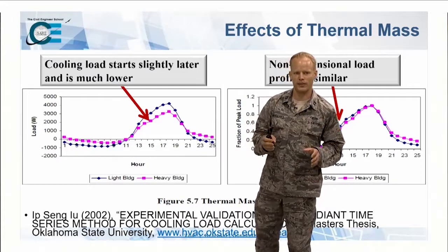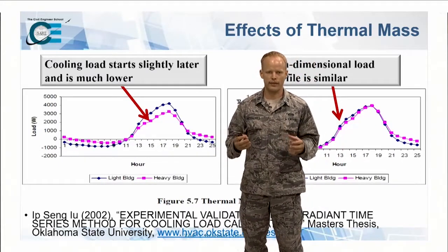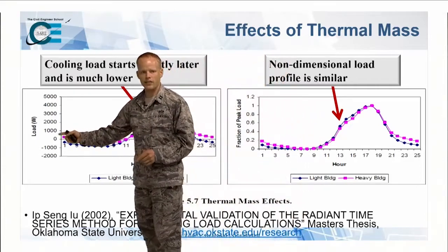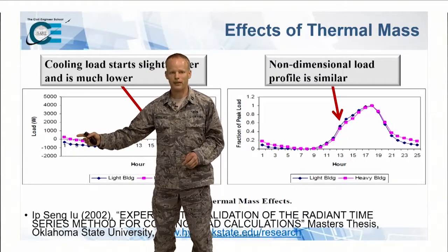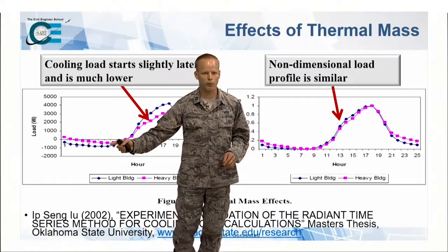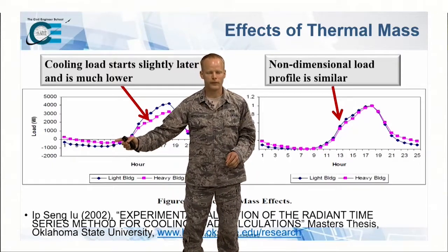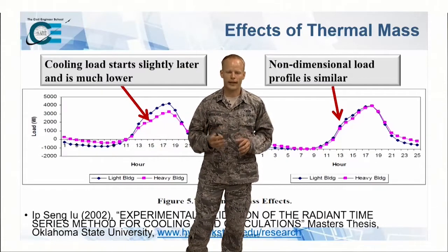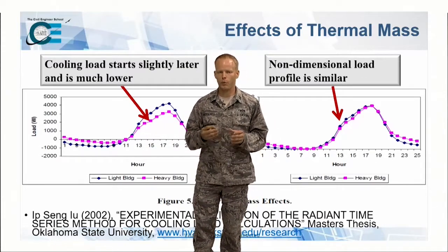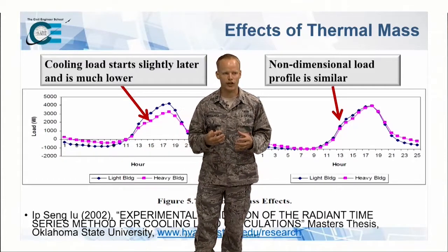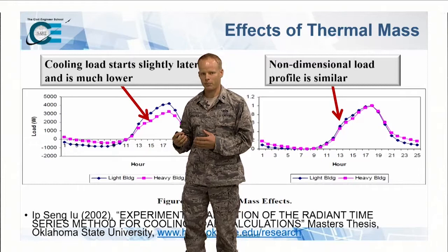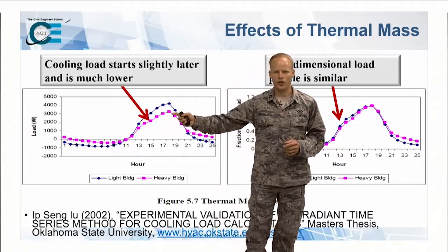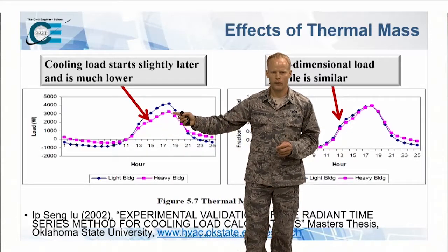But if we have thermal mass, well, at night, that thermal mass is going to get colder, and it's going to continue to get colder. So we look over here, and it doesn't decrease as much, following the purple line or the pink line. It decreases slower, but when it's here, now they're even. So when the temperature starts increasing, and it gets warmer than your thermal mass, that thermal mass is now going to absorb some of that energy rather than just passing it straight into your space. So it's going to absorb it, delaying it, and in doing so, it'll decrease your peak energy load.